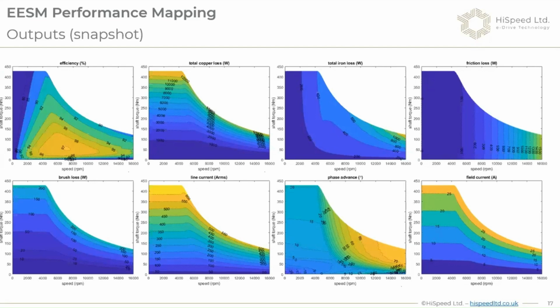In practice, you may get a bit of divergence. It's not always 0.5, and it's not always perfectly hyperbolic. It really depends on your inverter. But especially with the PWM, you have lots of points per cycle, so you would start simulating too many points to make it really time effective.